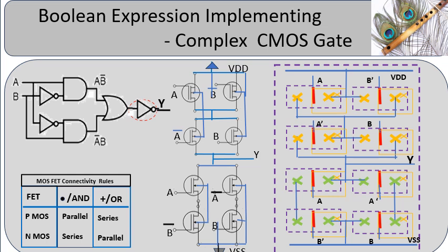For complementary inputs, provide inverters or check if they are available externally. Use consistent color layers in drawing the stick diagram. Avoid poly crossing metal, which would complicate the fabrication process. Adherence to design rules in drawing the stick diagram, symmetry and correct mapping of sticks to the schematic will ensure functionality and performance of the fabricated layout that is called a standard cell.